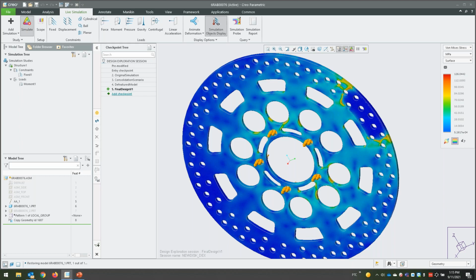So I guess in this case, we've decided that we need to reduce the material. So we're happy for the stress to go a little bit higher than what it was when it was 110. So we're removing the material, it's gone up to 125. I think we started at 140. So we've reduced the stress in this design. We've also made it simpler. Before it was an assembly, now it's a part. It's basically a laser cut part, right? Or if you know what I mean, it's a single plate. It's not multiple components, there's no welding. So that's also a benefit, okay?